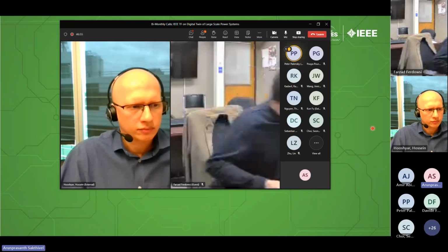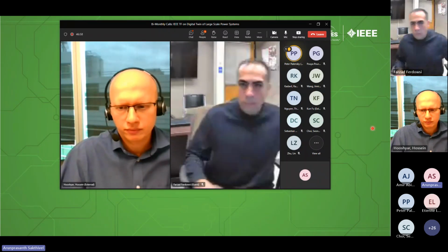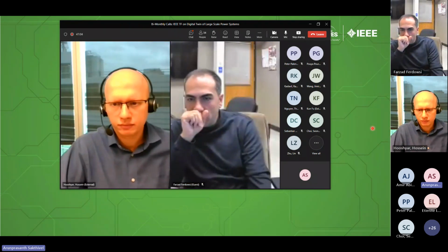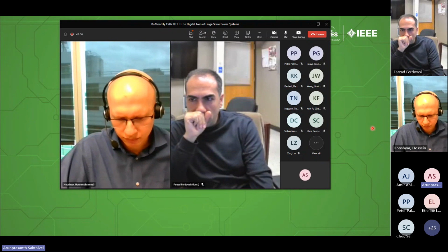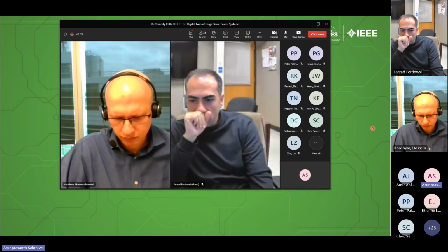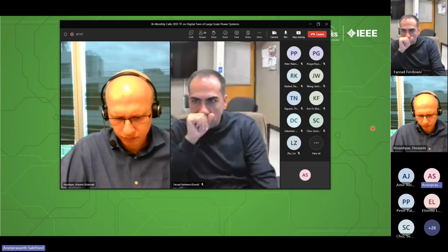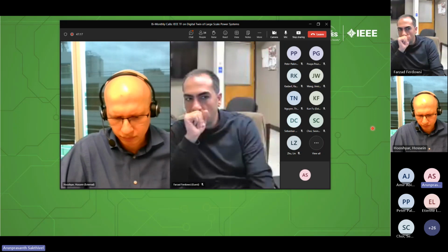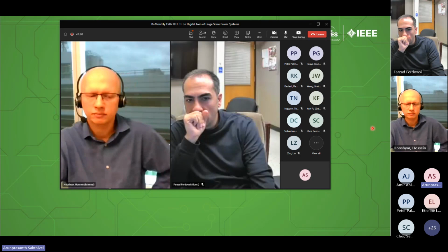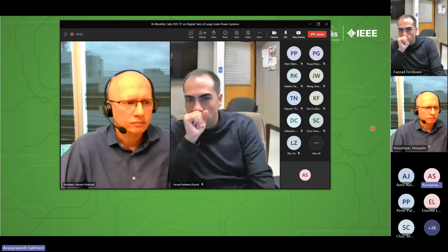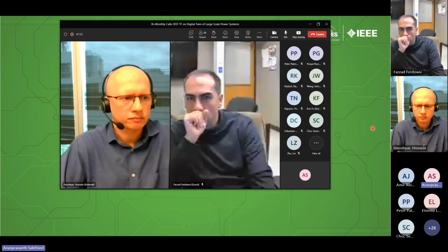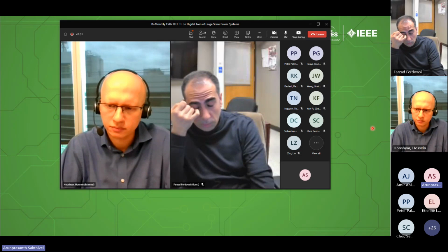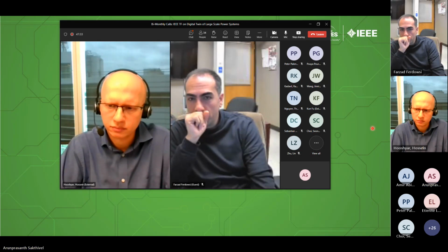Yeah, that is a good question, Professor Peter Polinsky. And yeah, the answer is yes and no. So basically, there is an export feature in RSCAD which allows you to export the data in PSSE format that we can use to model the TSA simulation. Basically, the TSA simulation in RTDS requires PSSE files, which are the power flow and the dynamic data files. So we need to generate the portion of the network in PSSE format to be used in that co-simulation platform.